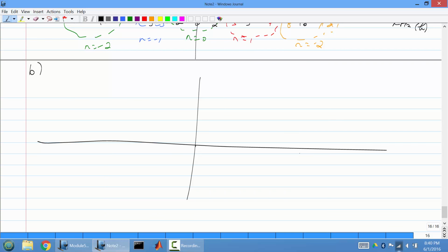So what's going to happen is that you have 0, and then you have copies at every multiple of 3. So we have 3, 6, 9, and then minus 3, minus 6, minus 9. All right? So at the very beginning, this is minus 2, this is minus 2, and this is kilohertz, right? This is F. So we have these two here, and then these are both S of 0 from the Fourier series coefficients. And then finally, at n is equal to 1, we have plus minus 2. So we're going to have 1 here and 1 here. So this is S1 and then S1.